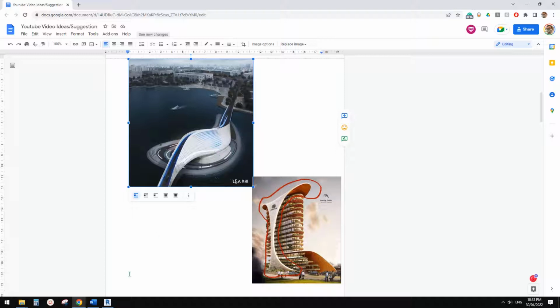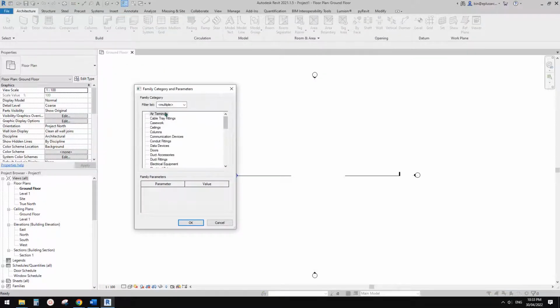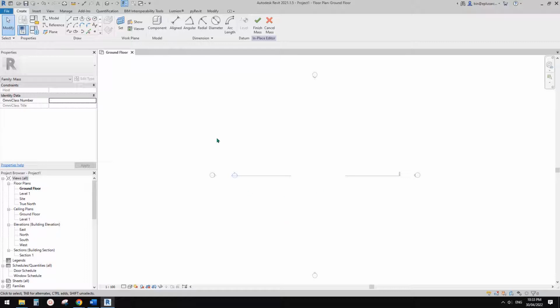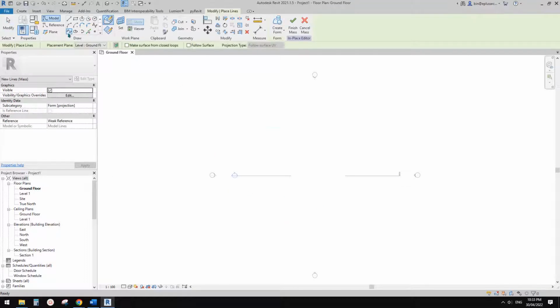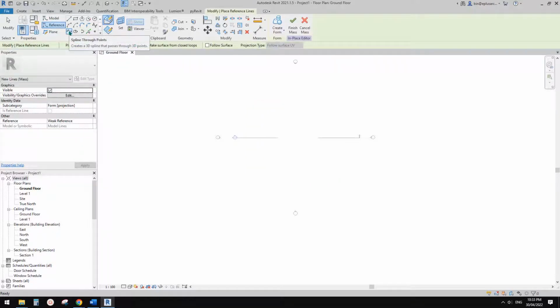And of course, I don't think I'm very good at the massings, because Revit is not really a perfect tool for this. But we will try. Okay, so let's start with model in place, mass. And so first I'm going to roughly create a path, and I'm going to use reference modeling, a point through, spline through points.